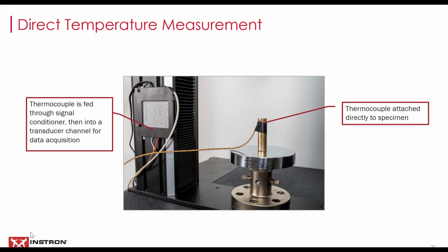This allows users to get more consistent results if they're performing tests on systems that have different chambers, and maybe those chambers have different specifications, different heating time, the thermal gradients may be inconsistent, and so it might be difficult, based on the temperature controller itself, to get consistent temperature at the specimen. So if you're able to test at the specimen itself, you're able to really understand and ensure that all your specimens are being tested at the same temperature. This becomes particularly important if you have temperature specimen components or materials.